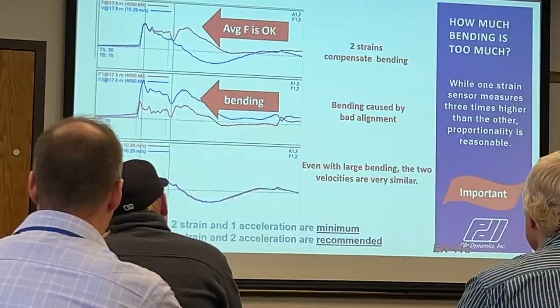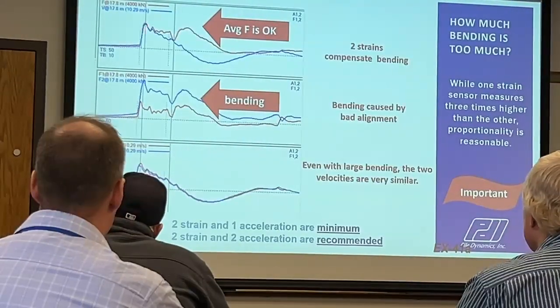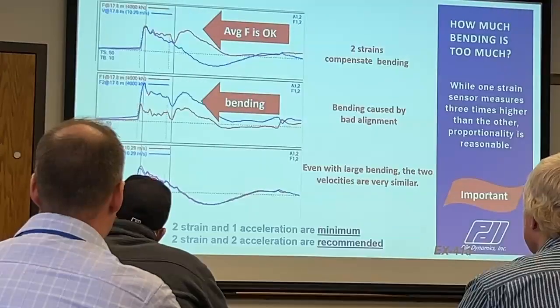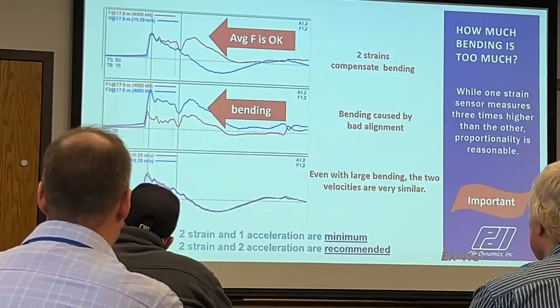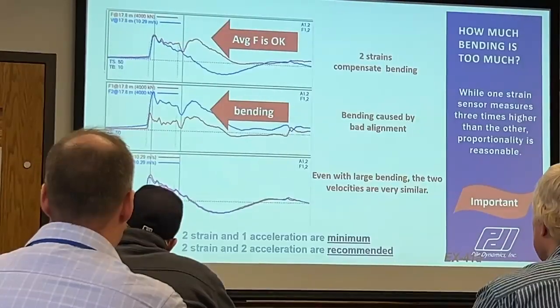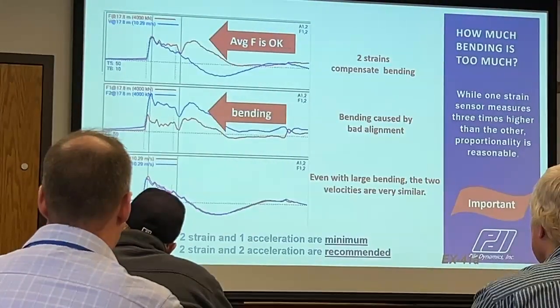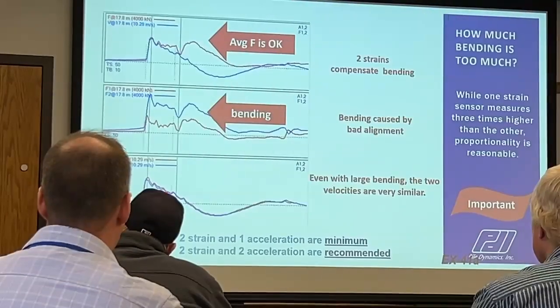So as the PDA tester, if you have this, you don't necessarily worry about this unless the numeric value of that peak is really starting to go above the yield strength of the pile material.